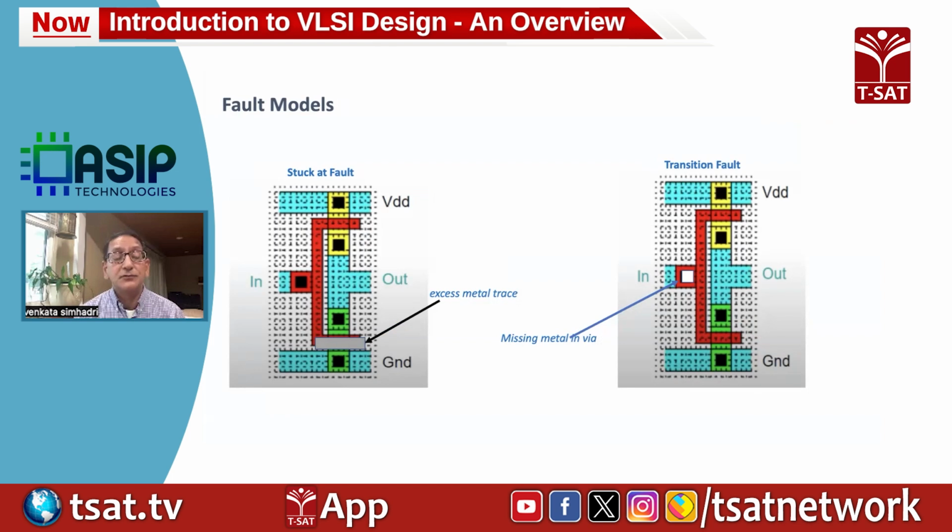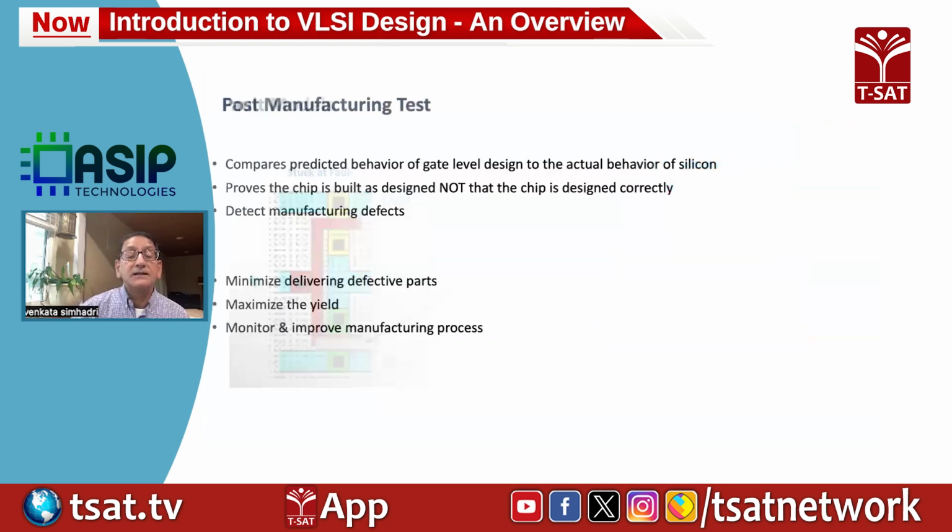We use fault models. If it is a short, it can be a stuck-at fault. If it's an open, it can be stuck at 0 or stuck at 1, as we call it. And then there are transition faults in the design. So you create fault models and a design for test methodology to detect these things on the tester.